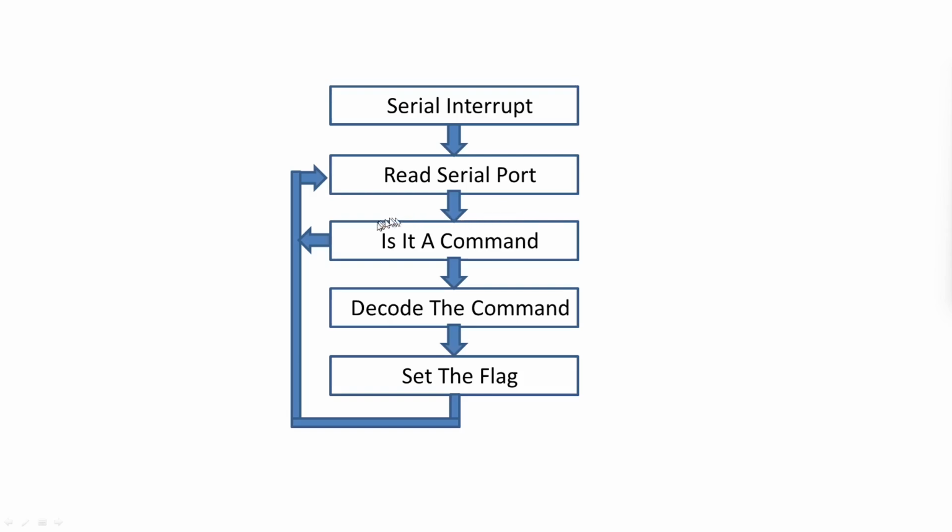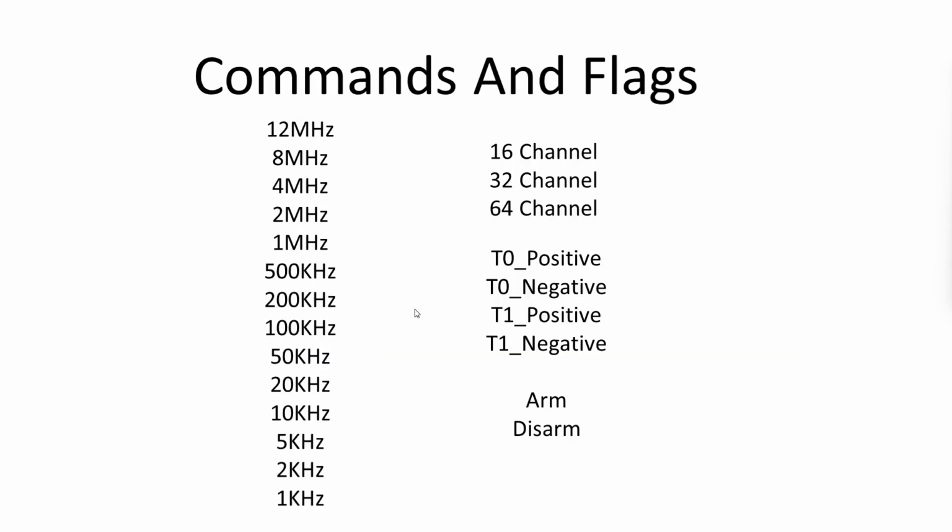So if it receives a carriage return, which is a number 13, I believe, it goes, oh, I've had a string sent to me, let's go and check it out. If you get in a 13, it says you've had a command come in. So it then decodes the command to try and decide what it is. Now the commands, if we quickly whiz back here, these are the actual commands. So these are the strings it will be sending.